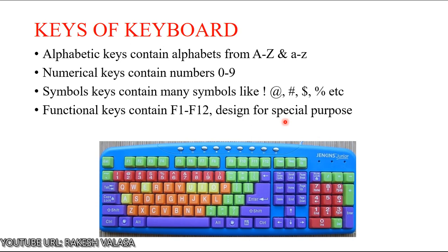Each keyboard or input device in general is connected to the computer by means of registers whose contents can be read by the computer. A keyboard has typically two registers, one to set a status bit when a key has been struck, the other to identify the key by its character code.